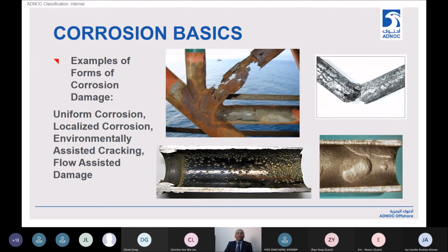What you see in the top left picture is a structural member of our offshore platforms. What you see is large diameter pipe, ranging from about 6 to 24-inch diameter, structural steels. They suffer from corrosion because of marine environmental exposure. There's corrosion occurring because of seawater and salty water depositing, with oxygen present in the atmosphere. You have aqueous corrosion resulting in metal thinning and loss of structural integrity.